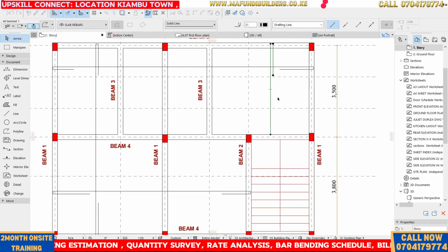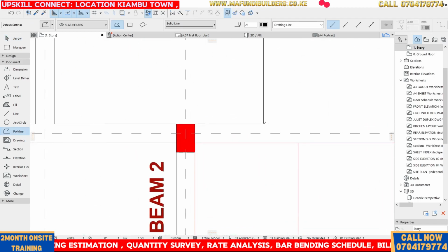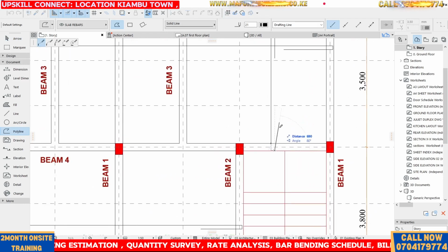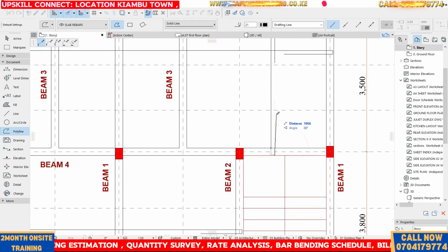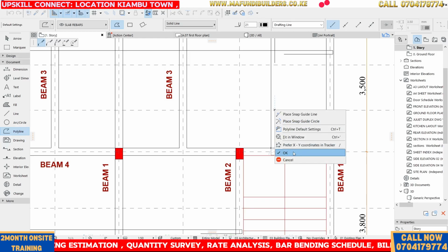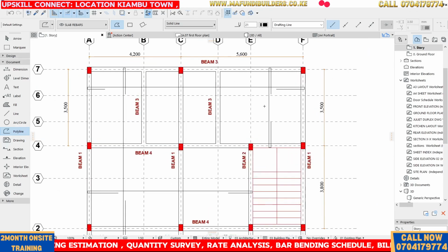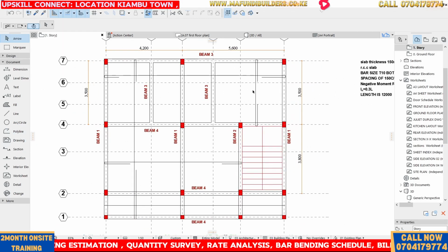Then now you can also pick up this. Make sure that's almost up to there because we have a concrete cover for the beam to be 25. Then here, guys, also you need to have 1200 there. So you're going to do 1200. Yeah, like that. So that's how. So this bar is going to be distributed for only this direction. So let's now start doing the distribution.